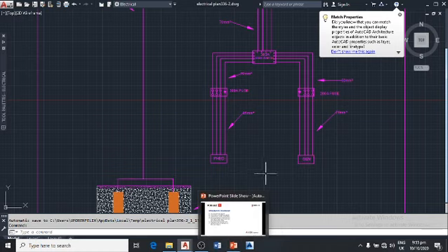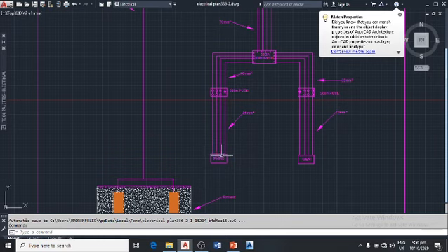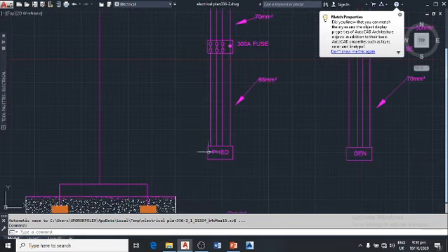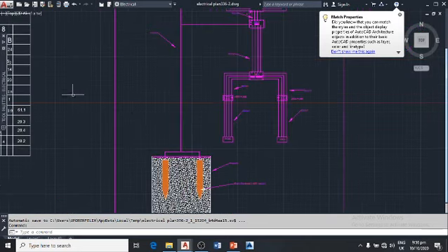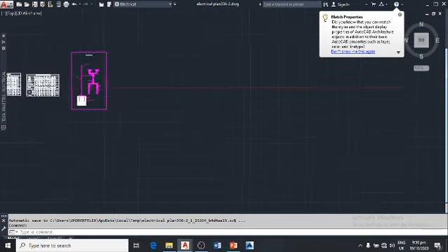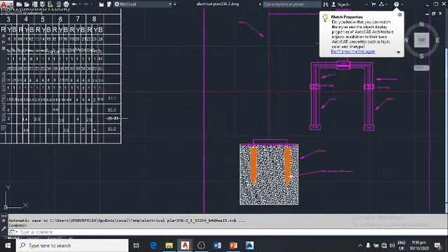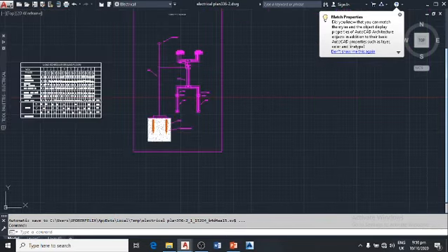So we're selecting our source as this. Looking at a PHED source, that's the NEPA source, or Power Holding Company source, we're using a 300 ampere fuse, in the sense that if we have about 500 amperes assumed load for the whole building, we have about 500 amperes assumed load.